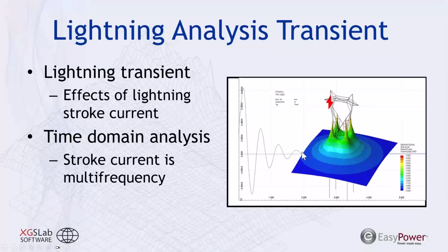You can also have a poor grounding system, and instead of this peak current going up and reflecting back down, it can go up and, similar to a wave, start to go down before it bounces back and increases again. So these lightning transient analyses can get very detailed to determine what's going to happen as the current's propagating through this metallic structure. And this could be applied to critical buildings in order to see if there's going to be a side flash, transmission lines and substations. All these are more critical infrastructure that you can evaluate with higher detail.